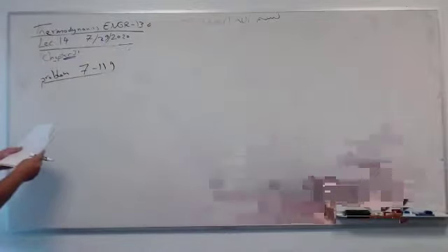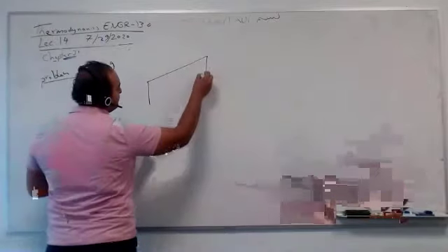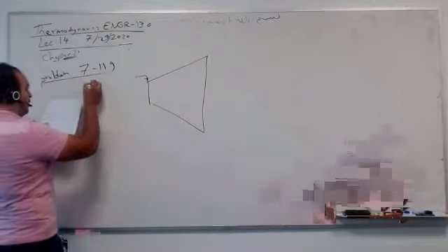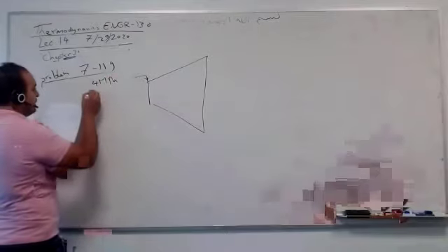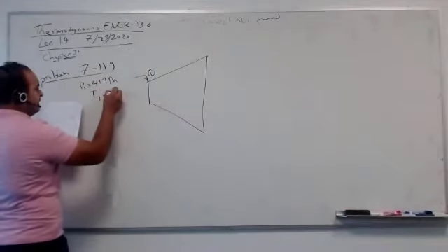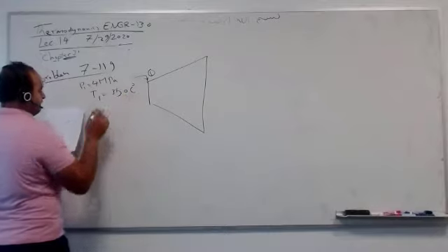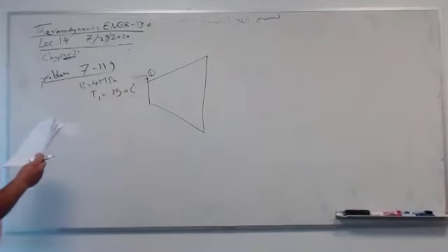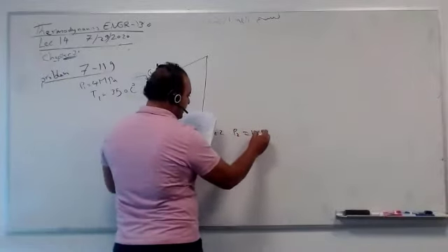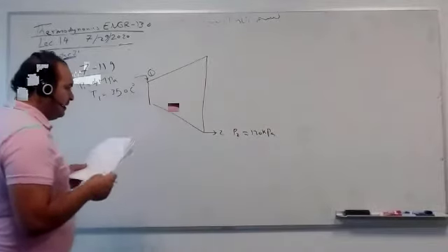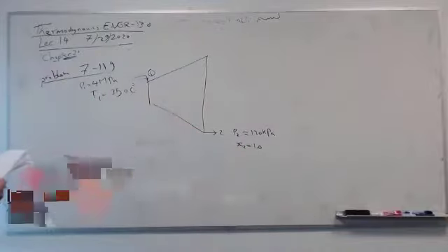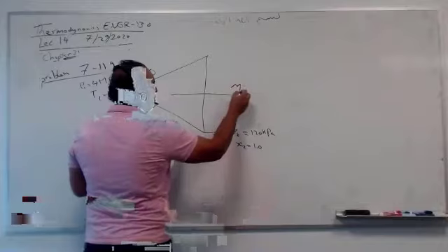It says we have a turbine. So the flow is going in with, I don't know, 4 megapascal. T1 is 350 Celsius. And it expands, going out with much lower energy. P2 is 120 kilopascal, almost 1 atmosphere, with quality x2 equal to 1. He wants eta turbine.